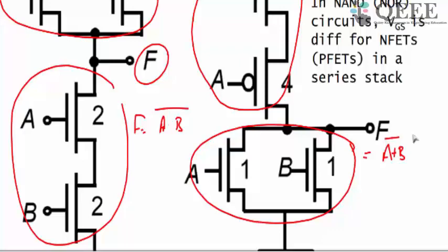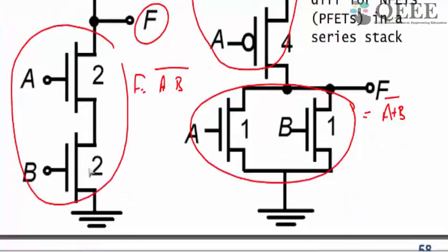If you look here, this is where the effect of the body effect comes. Normally in the NMOS transistors, you may connect to a substrate voltage. If you are not interested in applying any voltage, what you normally do is connect all the transistor wells to ground. Suppose you connect it to ground here, you connect it to ground here, right.